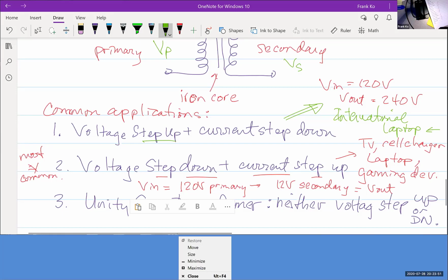So that's one of the most common applications for all diplomats, anybody who works in an embassy, anybody who works in international business that travels to foreign countries, and foreigners coming traveling to here, they have 240 volt devices. So they have to use a voltage step up transformer, okay? Whereas the rest of us, for the most part, what we're going to encounter is going to need a voltage step down for our devices.